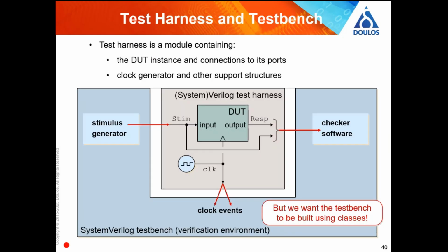You would use SystemVerilog classes not only to generate your test bench, but to represent your transactions, and also to generate the other components in your test bench as well. And we'll see an example of that in a minute.